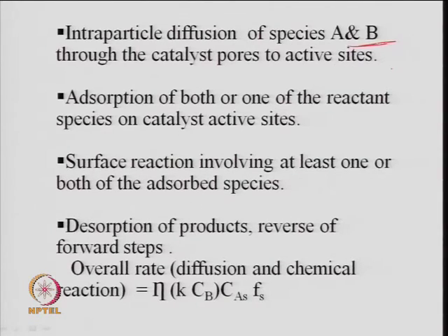Again, one needs to find the pellet effectiveness factor, which will be based on the Thiele modulus, right. The Thiele modulus will depend on the size of the catalyst particle. All these factors we have learned before will be utilized here also, because the effectiveness factor is very important and we need to control it. That is, we need to maximize it, approaching 1 if there is no diffusion resistance, so try to minimize the diffusion resistance, right.